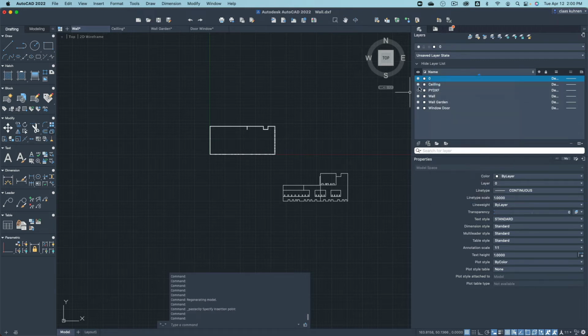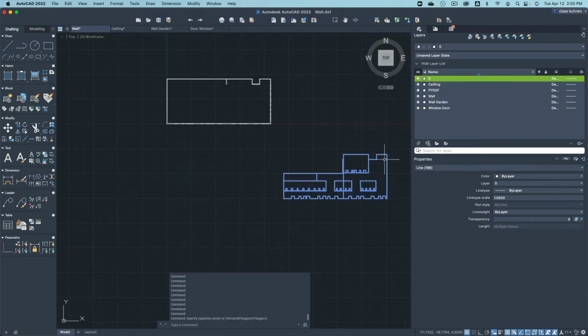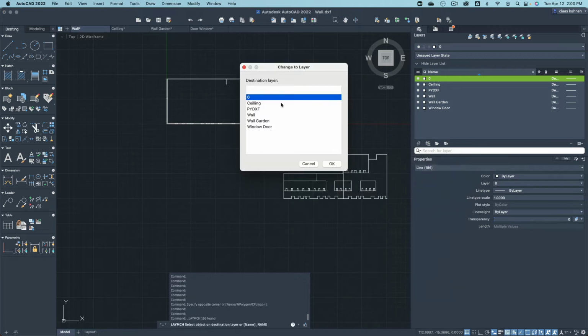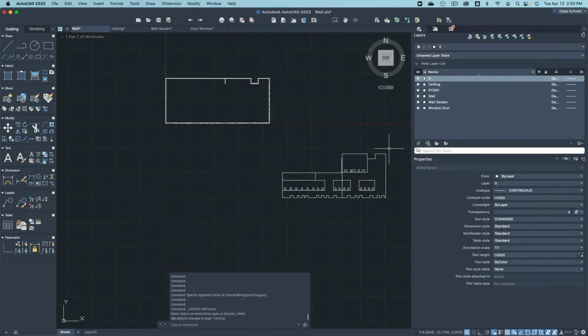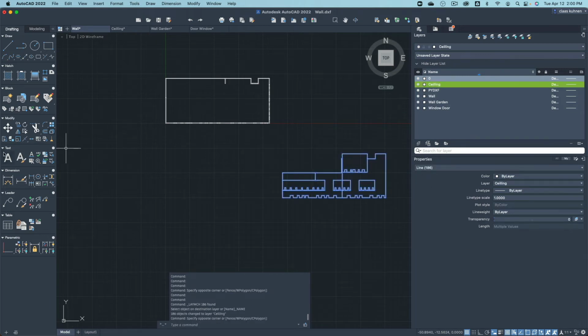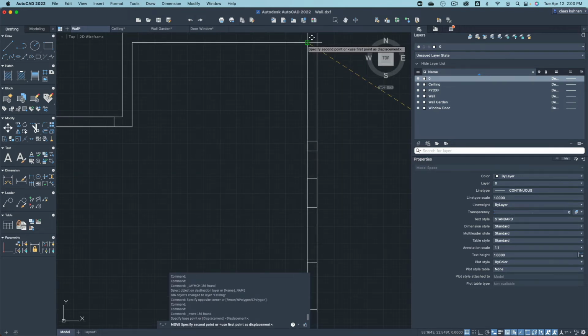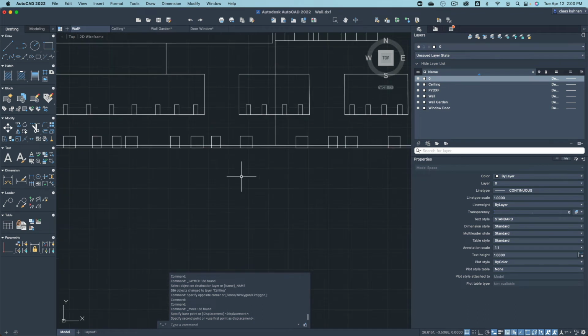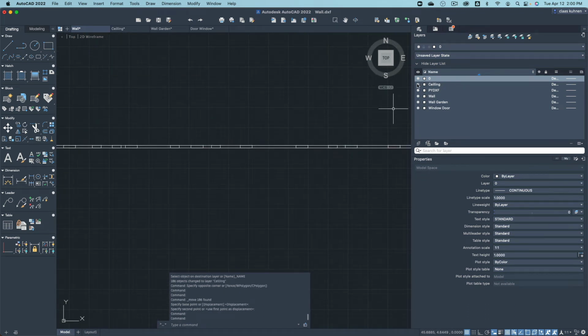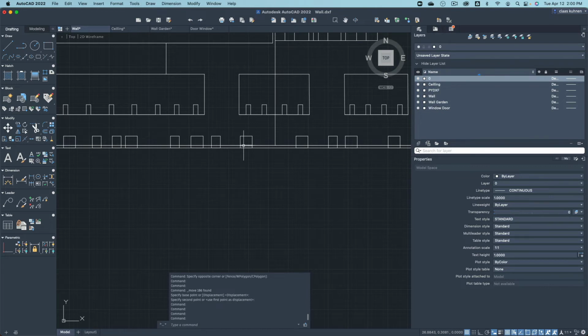then no, it does not actually do this automatically. I was curious. But we know we can simply move it to ceiling there. And then how do we line this up? I mean, this is extremely complicated. We just snap the interior wall edge with the interior wall edge. Bang. There. You see now here also, again, now what I said with the ceiling, how these lines here I didn't do in the Blender model, because it will line up now with the window part here. There we see how this extends it.